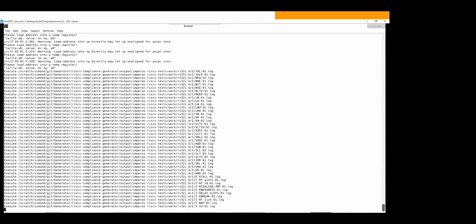So having looked at that on the GitHub, which you can download, I've now got it on my Linux machine here, so we can actually have a look at it. I've downloaded the test directory from the GitHub, and we can see from the changelog file here what the current versions are that are supported by the different tests in it. And then it's a simple make and bash mechanism, in the same way as the existing RISC-V compliance tests. And you basically say you make, with the makefile that drives it.